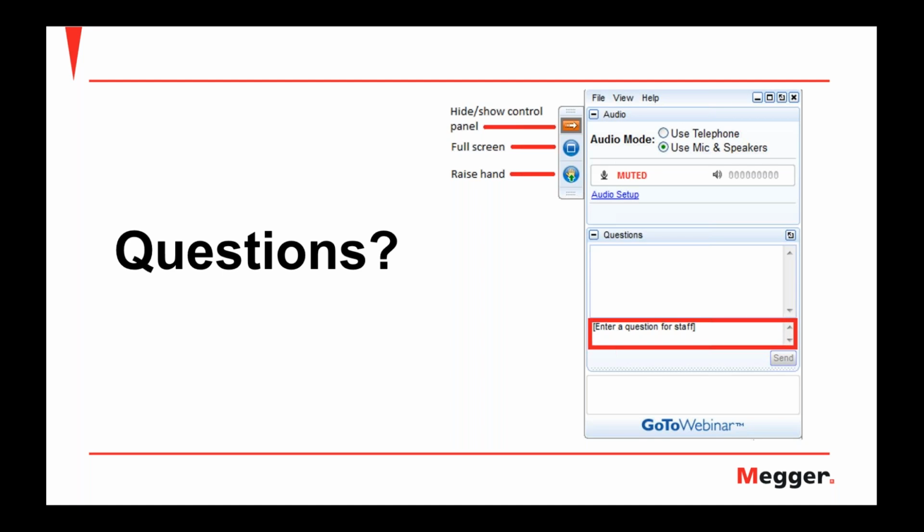Now, as far as testing the specific gravity, it's basically a measurement of how charged the battery is. As the battery discharges, that specific gravity drops. So you can have some batteries that have specific gravities of 1.215, some with 1.3. Again, you want to look at that data sheet.